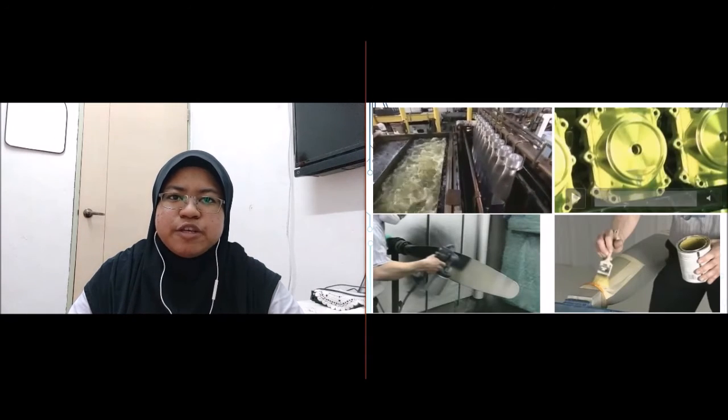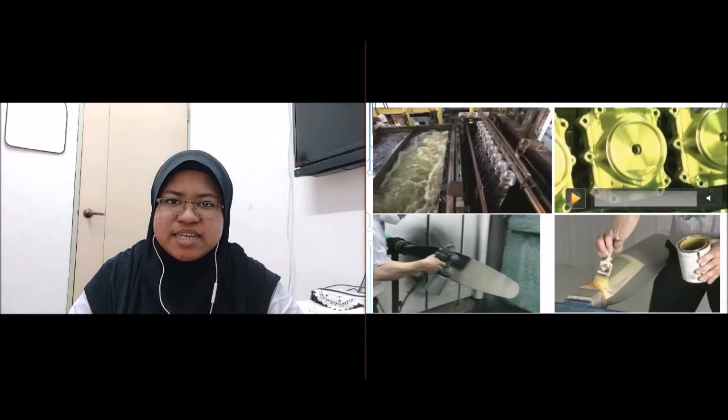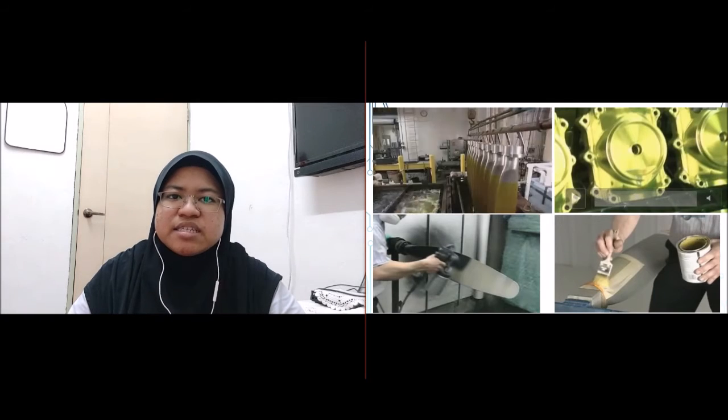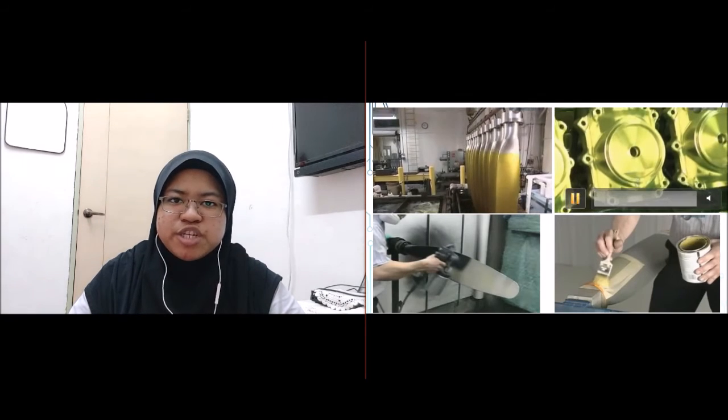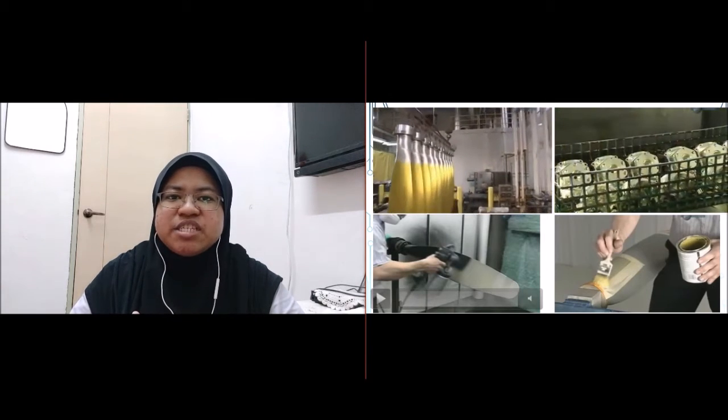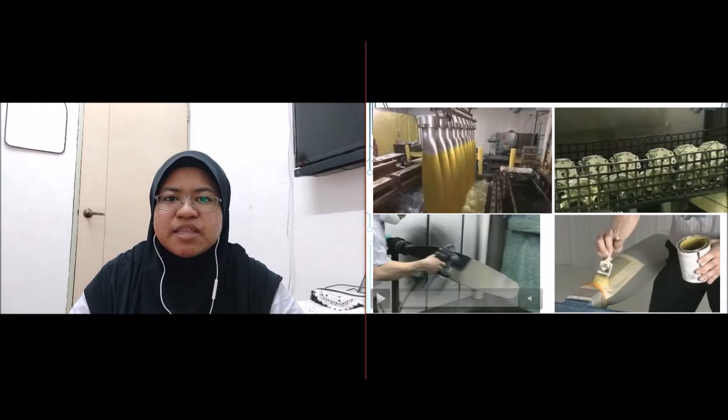Then the blades will be put into a bath of water and chromic acid. This procedure will seal the pores in the metal to fend off any corrosion. The critical parts are dipped into the fluorescent solution. The fluorescent solution is used to reveal any imperfections. After rinsing, the parts are inspected under black light.